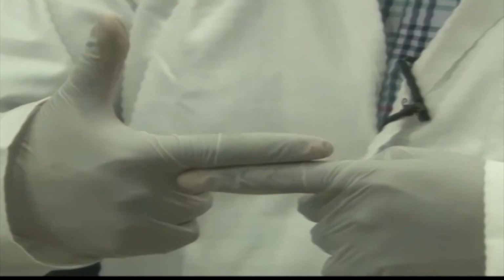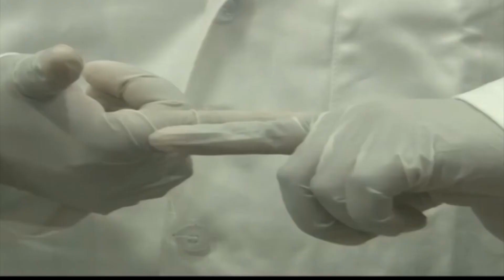What will happen? It will displace the nozzle. If this overlap is not here, this is 0.1 and this is 0.1, the nozzle will touch this one and it might displace the nozzle, the part might distort. So some overlap should be there, so there has to be some gap for the nozzle to work in. Some gap at this surface has to be there. So for that, this overlap limit is given. This overlap limit can be 15% or 20%.